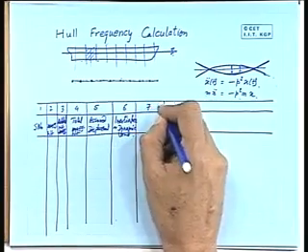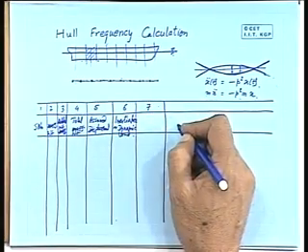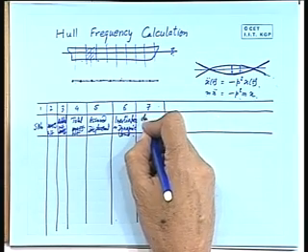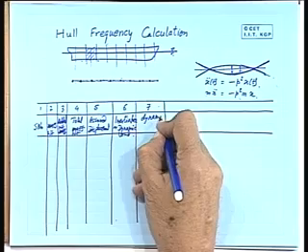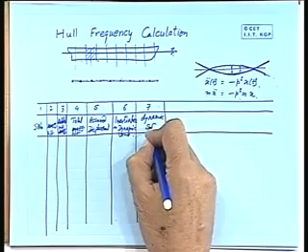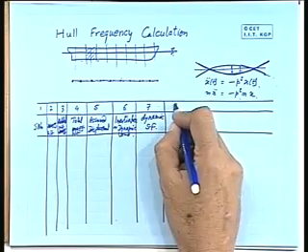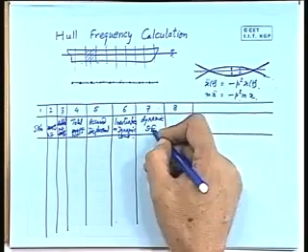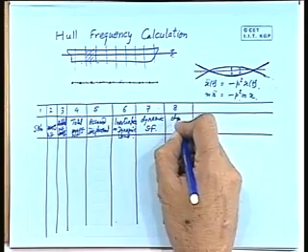Then you have column 7. Integrate this along the length, you will get your dynamic shear force. Integrate the shear force once again, you will get the dynamic BM.